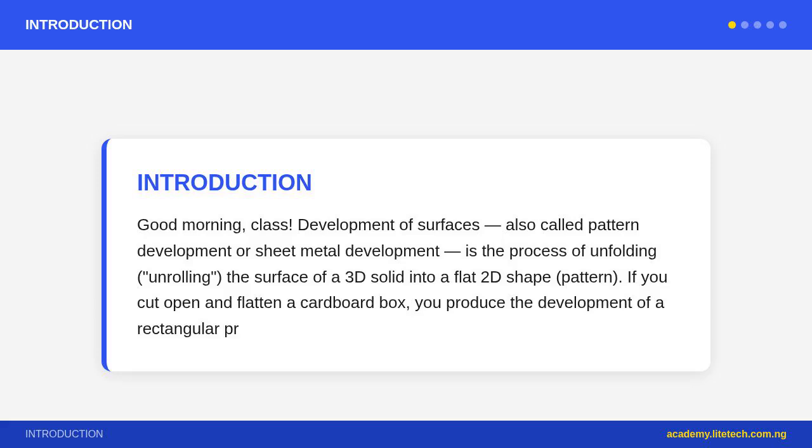Nigerian manufacturers of ventilation ducts, packaging boxes, cooking pots, and tin containers all use surface developments to cut flat sheet metal or cardboard into shapes that fold into the finished 3D product. WAEC Technical Drawing tests development of prisms, pyramids, boxes, and cylinders. A right prism is a solid with flat, parallel top and bottom faces, the bases, and vertical rectangular side faces.